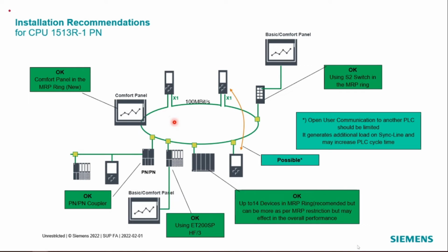It worked okay. So if there are configurations with a smaller number of IOs, you can also consider it, but it has to be checked before confirming to the customer, because there can be performance issues since it's not recommended. The recommended number was 14, but if there are fewer IOs, you can try for that. It's also mentioned in the manual itself.